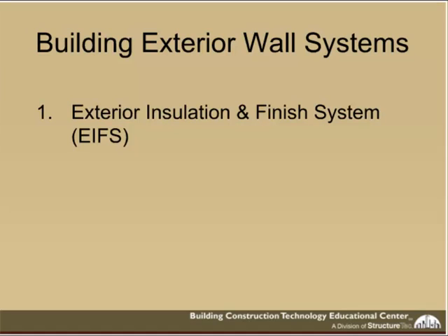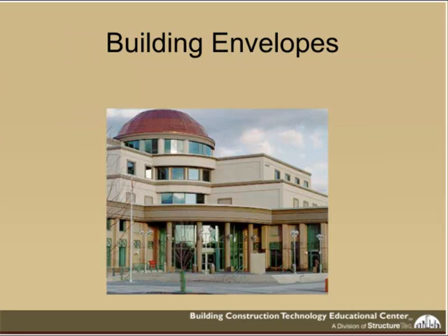So Russ, could you give us an introduction on what is an exterior insulation and finish system? The exterior insulation and finish system, commonly called the EIFS system, came out in the 80s. It was a lightweight, inexpensive way to imitate more expensive finishes. It was a non-load-bearing system that did not carry any superimposed vertical loads. This photo shows you an example of that. This material here is the EIFS system. To get it using conventional materials, you'd be using very expensive stones and similar materials.